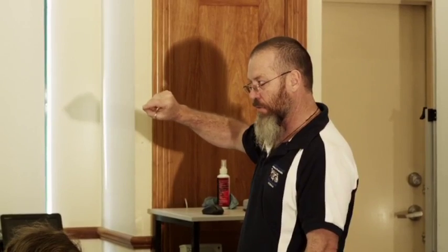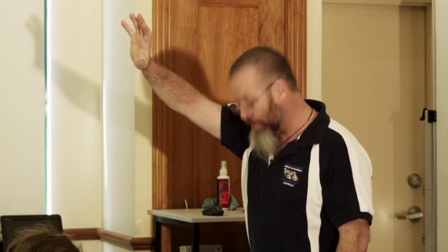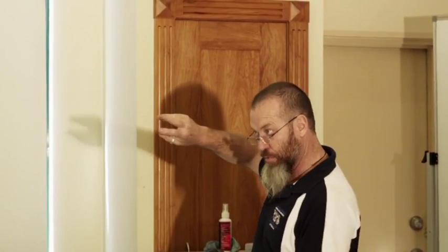If, say, you were doing a lintel connection, a lintel to the stud which is actually connected to the plate, which we'll have a look at in a minute, you select it from that second row. If you're doing your plate to your first floor, it says single or upper story, your upper story bottom plate to the floor frame, you get it out of that third row.